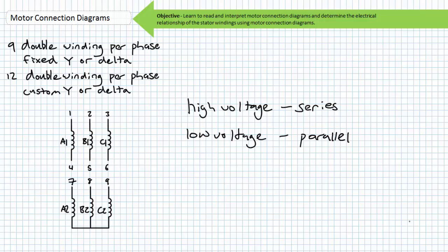This way, electrical power consumption, being the product of voltage and current, is comparable between motors utilized in either high voltage or low voltage configurations. In the high voltage configuration, voltage is higher, but current is lower. In the low voltage configuration, voltage is lower, but current is higher.